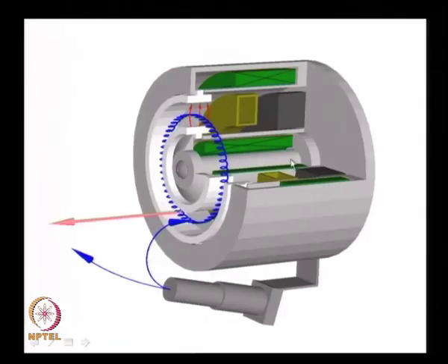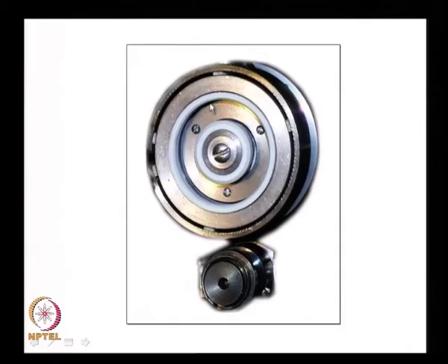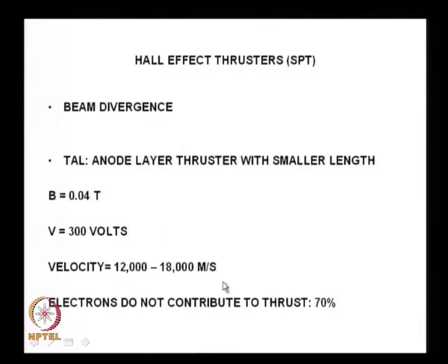Well, this is the picture of a Hall effect thruster. This is where the electrons are generated using a cathode. It enters the annular gap over here. There is a strong magnetic field in this particular gap, and therefore the electrons spiral, you have an anode here which pushes the thing out and you get the thrust over here. This is the face view in the annular gap, through this the xenon comes out and you get the thrust. This is the cathode which generates the electrons.